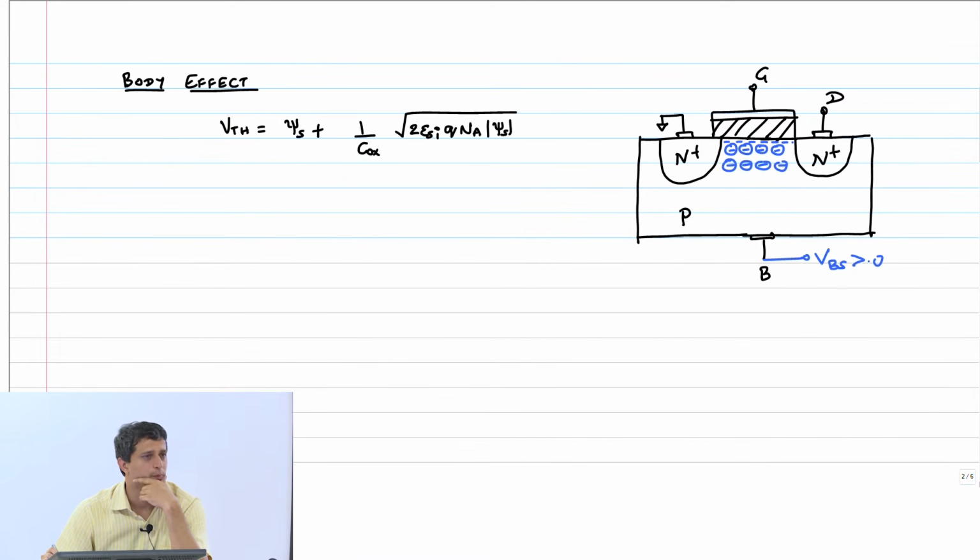The theory behind this body effect is very complicated, so for the purpose of this course we are going to abstract it out, and we will treat this body terminal like a back gate. There is a depletion region, which is basically like there are no free electrons, you just have an electric field from positive to negative charges, right?